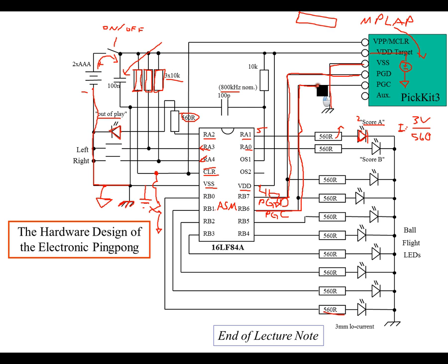if you look on your data sheet, you can see these. You connect it to your clock. Now, when you go to program your chip with MPLAB, your data and your clock are going to toggle on this line, and it's going to configure your chip. Once it's configured, it's going to be remembered because it's programmed into flash, which is non-volatile memory.